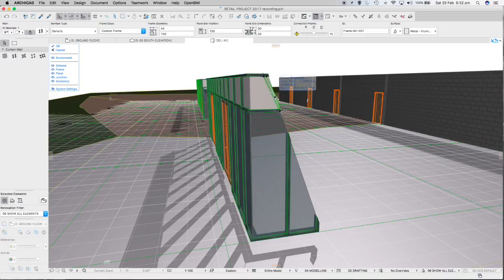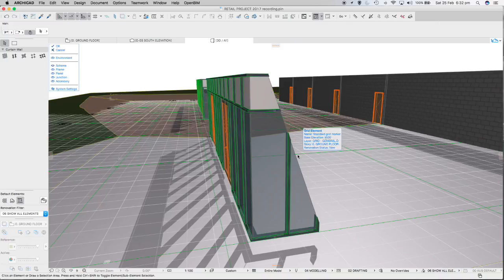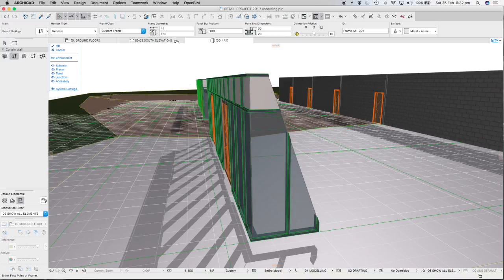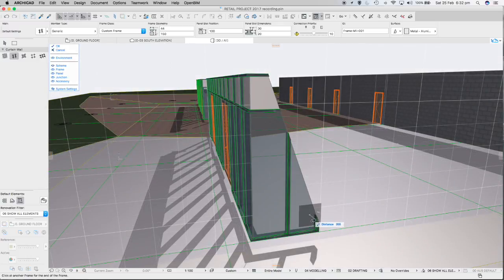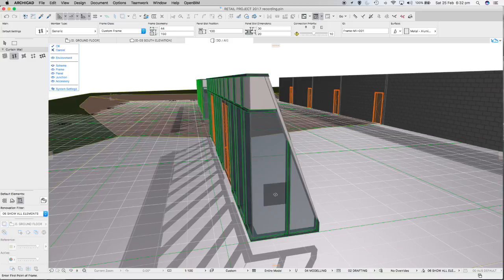You see when I highlight it, through there. And I think I'll delete that one. I'll show you maybe curtain wall frame tool. All the settings are the same. If I come down here and try and pick somewhere along here, oh, it's done it for me this time. That worked. That's good. And somewhere up there.